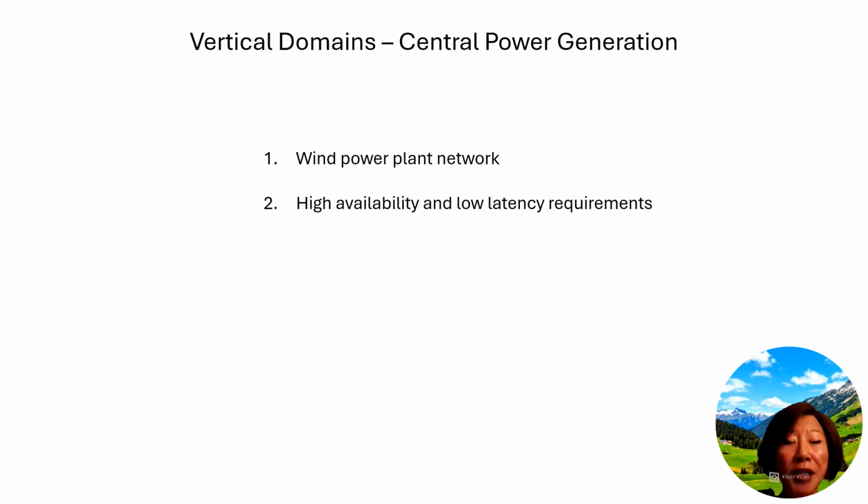The low latency requirements are met through a combination of radio and network optimizations. This might involve techniques like edge computing, where control functions are moved closer to the turbines to minimize network delays. The system also employs advanced scheduling algorithms that can prioritize critical control traffic over less time-sensitive monitoring data.